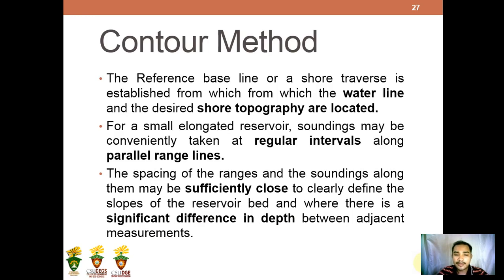So contour method, so the reference baseline or a shore traverse is established from which the water line and the desired shore topography is being located. And for a small elongated reservoir, soundings may be conveniently taken at regular intervals, no, along parallel range lines.